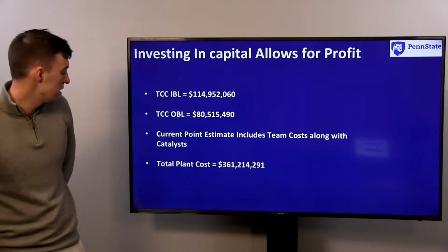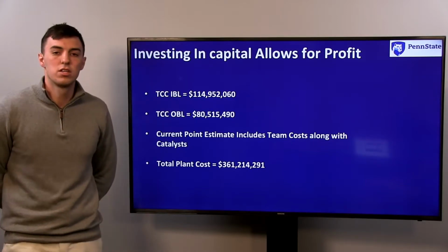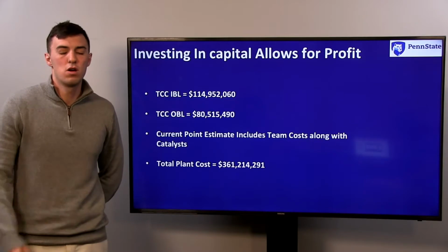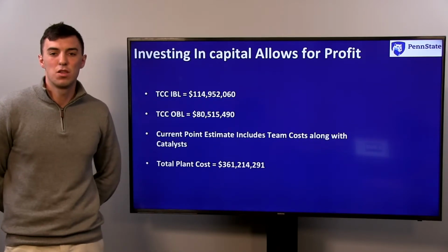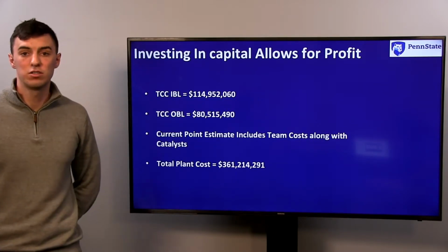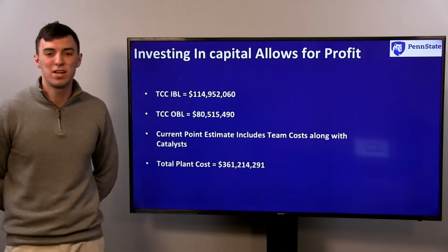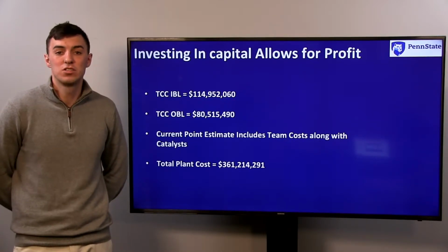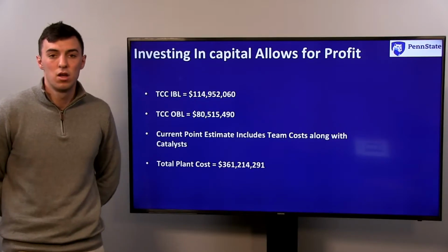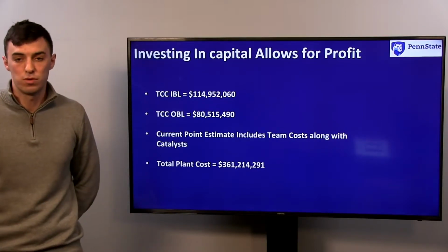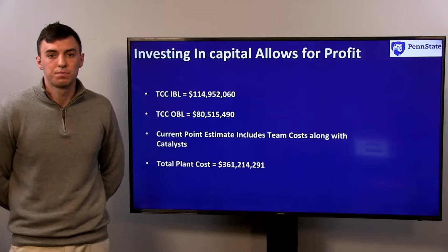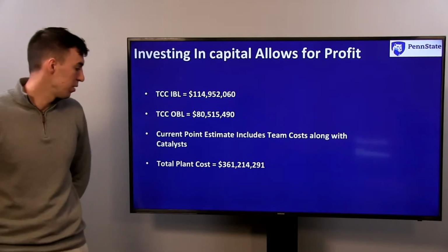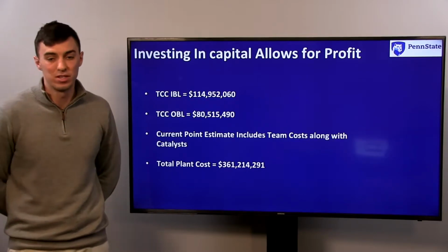The last part we had was the total plant cost, and all the costs so far. There was an inflation of 3% for 3 years, and a contingency plan of 25%. So we had to multiply what we had so far, what costs we had, by 0.34, and add that to the total cost, which gave the total plant cost to be over $360 million.